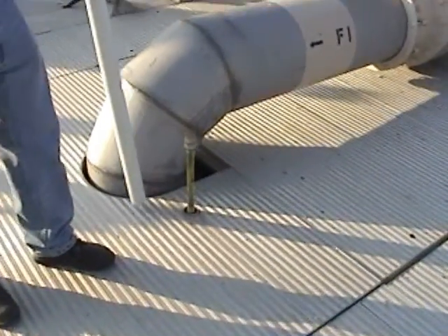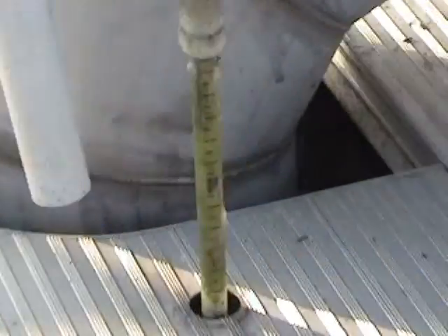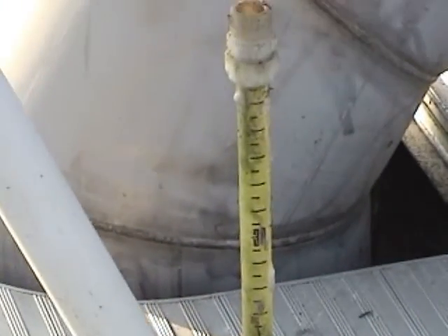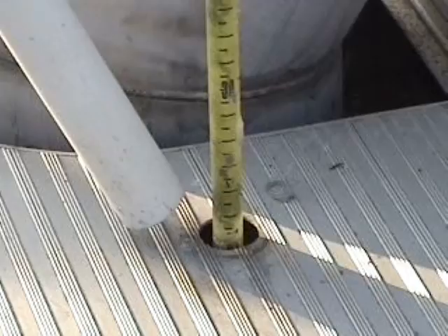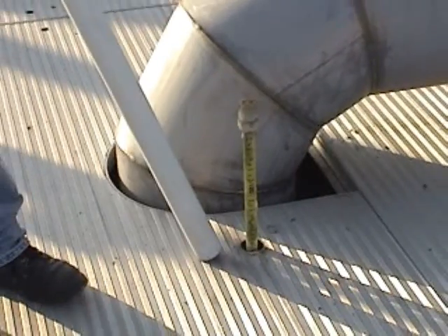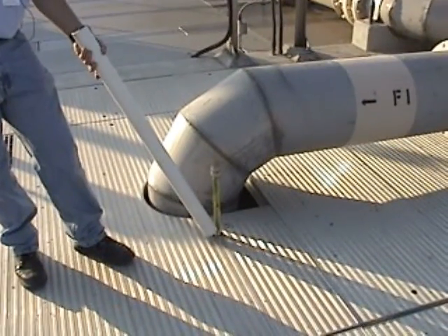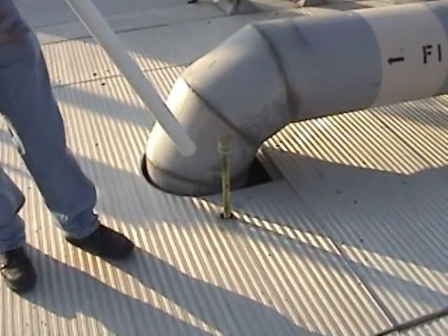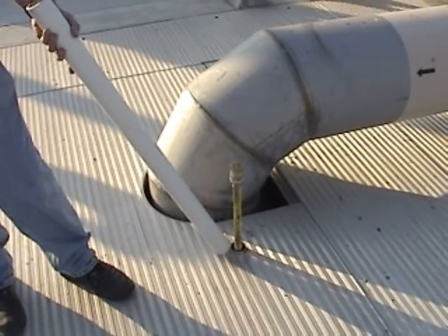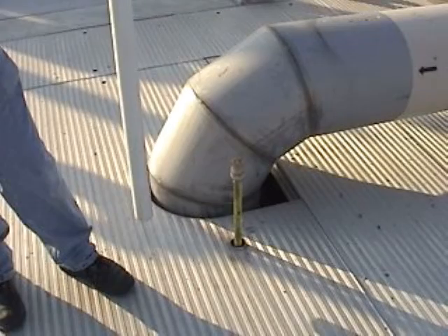These tubes are attached to the discharge of this pipe, which is the secondary effluent coming from the flock tank. There's a ping pong ball on the top that floats on top of the water that's in this pipe. So this pipe is connected up to give you an indication of the water level in the filter. And in theory, the ping pong ball floats up here and it tells you this filter's plugged up. The problem with that is if you ever have the filter plugged up that badly to where you can see that ping pong ball, you have a very, very significant problem.